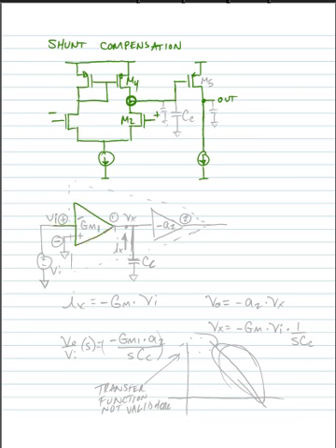In other words, we can put an input voltage here, and we can make it differential, I suppose. So let's do something like this. And then we go into our second stage, which is composed of transistor M5 here. So we can say that this has a voltage gain that's equal to minus A2. So we'll call this GM1 and minus A2.